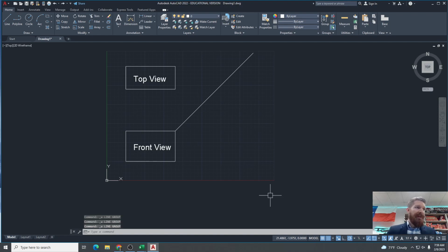Okay, that's one method. Another method. Let's see another method. You can use X lines to box in. So X lines, or rays, as were discussed in a previous video. You can create the construction lines for those. They can also be trimmed before your finished view. And then here's a method I really like.